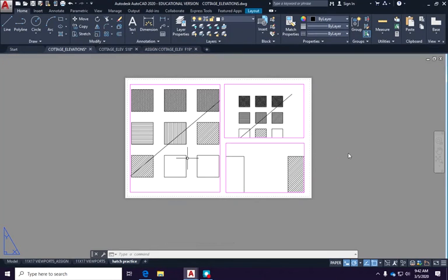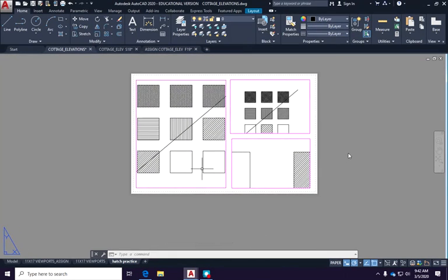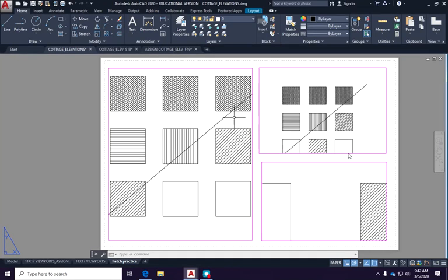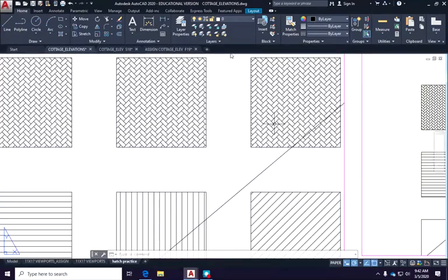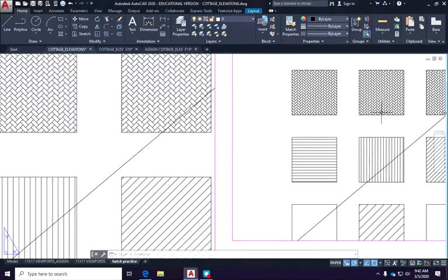The ones that are going to look like this, that's the point of annotative. If you zoom in and look at your viewports, the first 2 sets of hatches were the architectural ones, and these were the user-defined. When you change, graphically, this guy looks big, and this guy looks small, and that guy looks big, and that guy looks small.